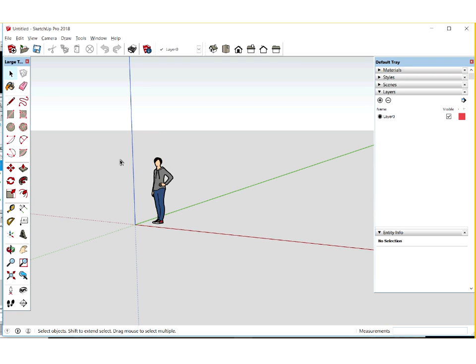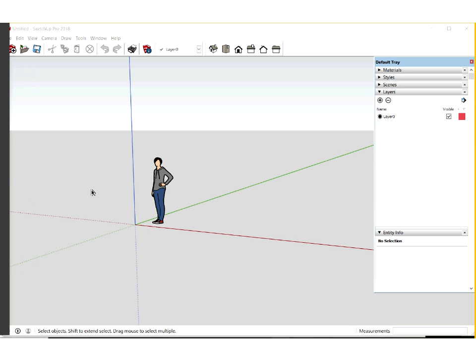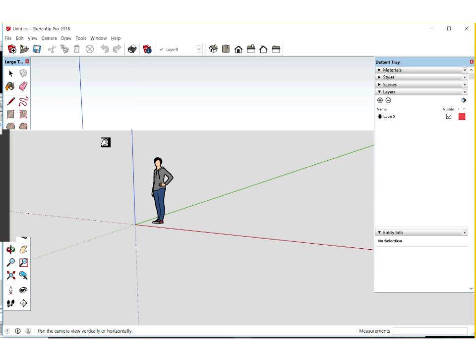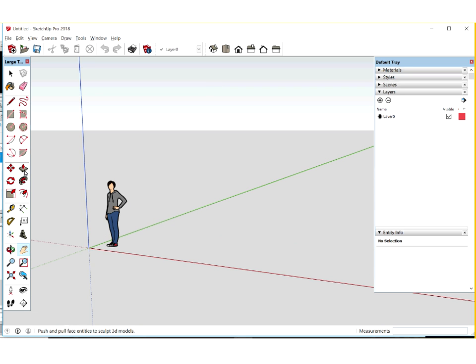Now, what we'll do is start with the basic shape. I like to build a floor area to work on. I think for interior design, it makes sense to build a structure similar to what we would build in any project that we're working on. So we'll start this with the rectangle tool, and I'll get you to work along with me here. After we've built a few things, we're going to group them, and we're going to label, and organize our file as we go along.